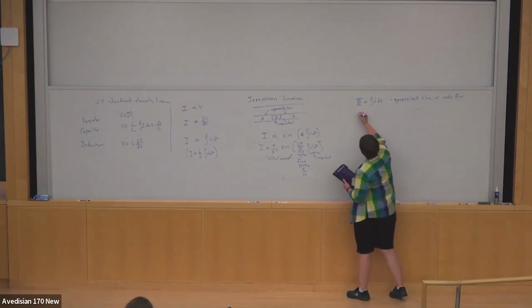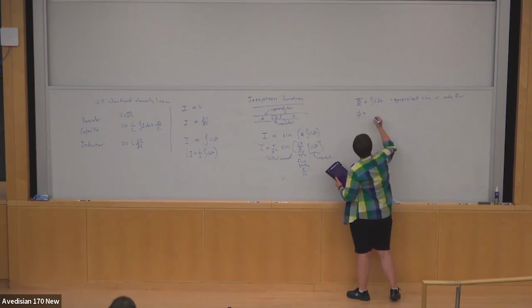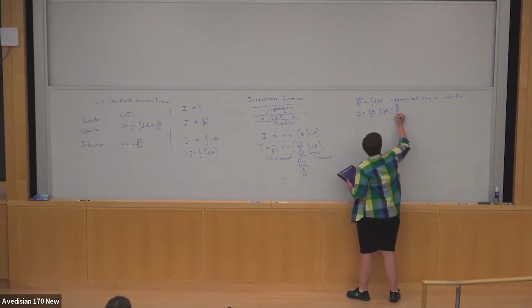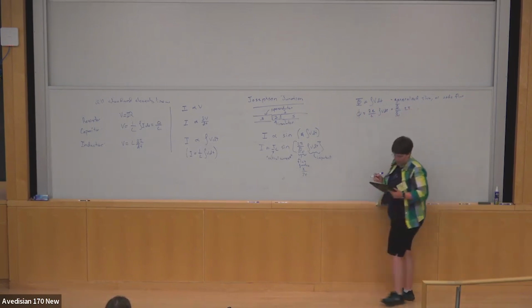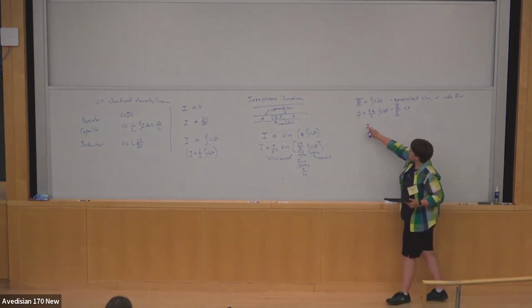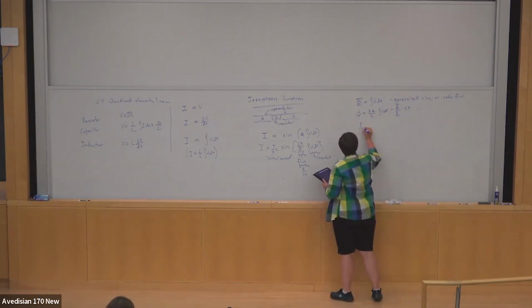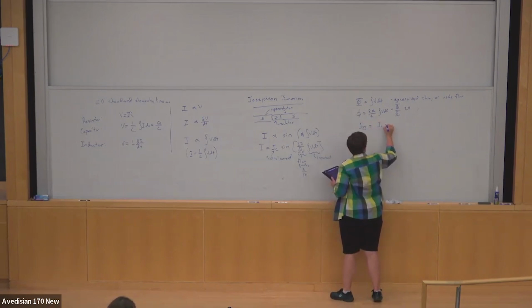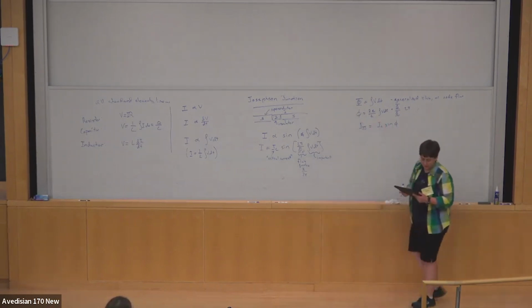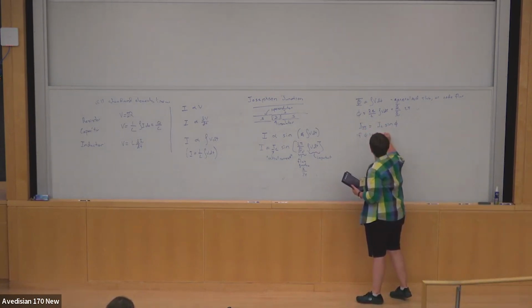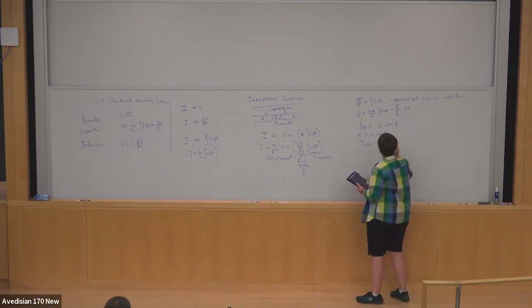And it's also very convenient to write the alternative form where you normalize it. So 2e over h bar, the integral of v dt, which is phi over phi naught times 2 pi. And so this is the nice simple coordinate in which the equations for the Josephson junction are easy. So I_JJ is I_C sine phi. And if phi is small, then the current in the Josephson junction is approximately I_C times phi.